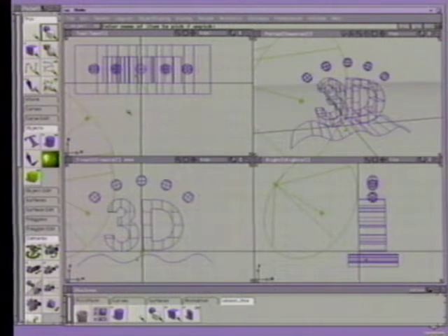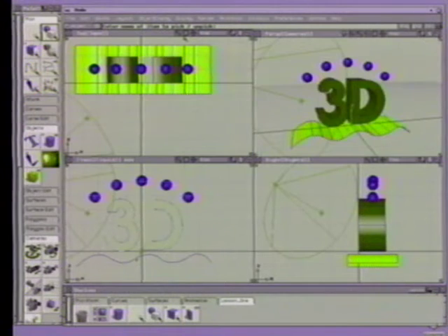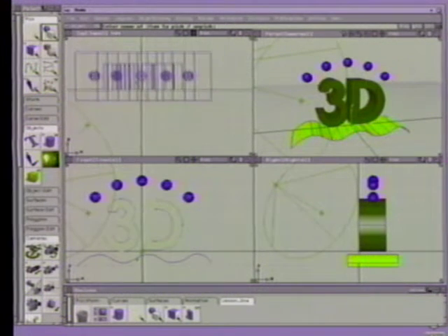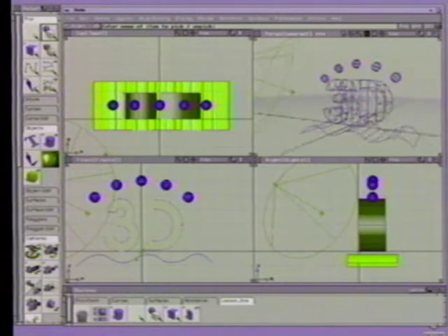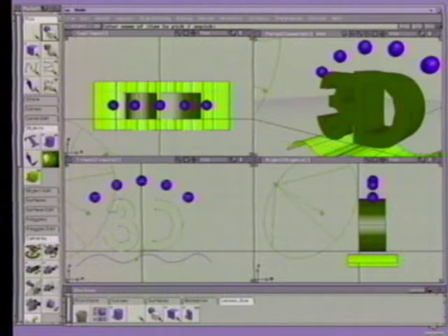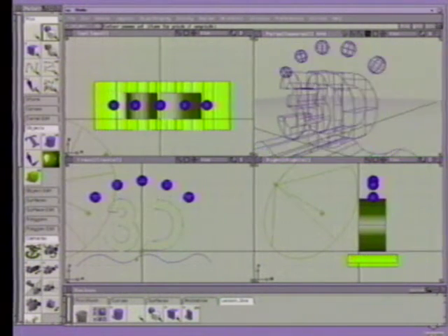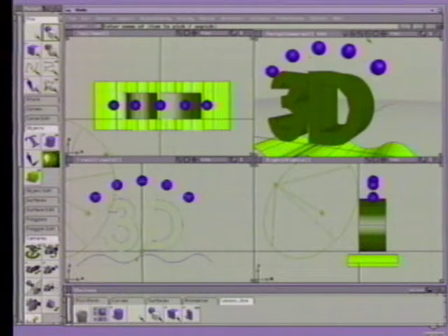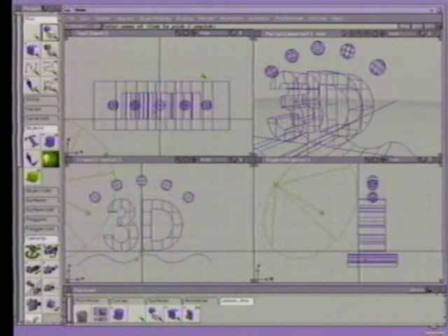Another display option is to see your objects shaded. From the display menu, select Toggle Shade. After a moment, all 4 view windows show shaded views of the geometry. Use the Tumble View icon to see how the shaded mode works when making view changes. You can model in a shaded view and you can make view changes. From the display menu, select Toggle Shade to turn it off.